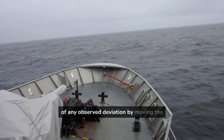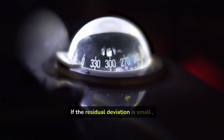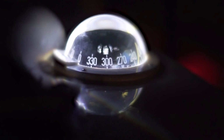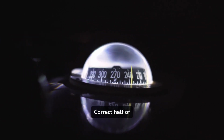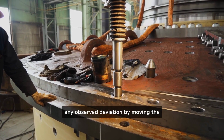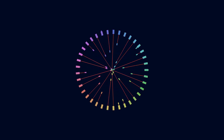Correct half of any observed deviation by moving the B magnets. If the residual deviation is small, leave it as is, for example, 2 or 3 degrees. 5/ Come to a north magnetic heading, 000 degrees. Correct half of any observed deviation by moving the C magnets. Also, if the deviation is small, leave it.